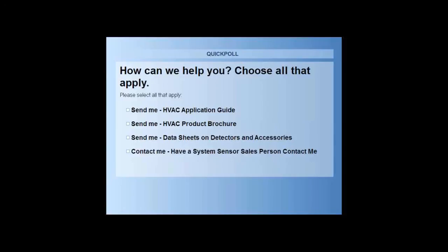And just ensure that the sensing element protrudes into the duct, that it's properly mounted, and that the installation through the duct is right in the middle and is sensing as much smoke as possible, or as much of the air that's going through as possible. But there are not any hard specific requirements for pendant mounting and the appropriate size of duct or damper that it can be installed in.